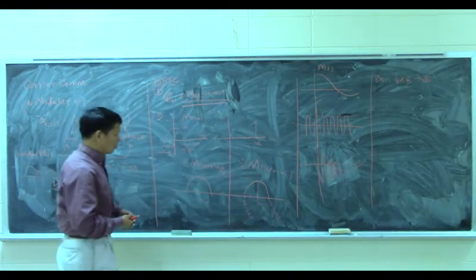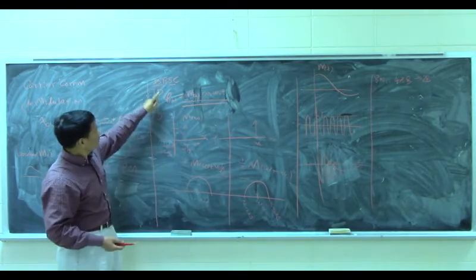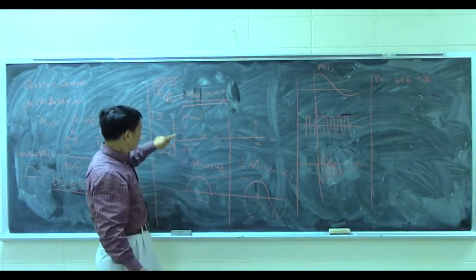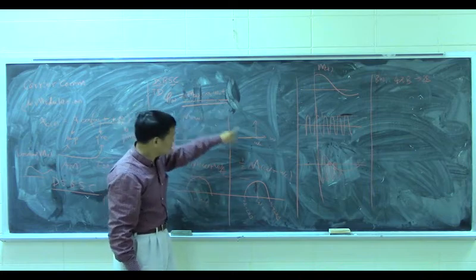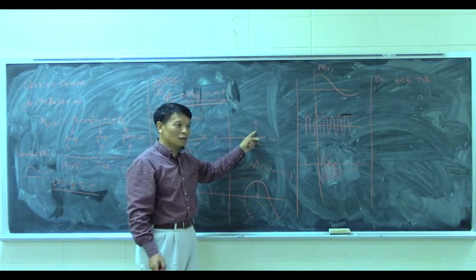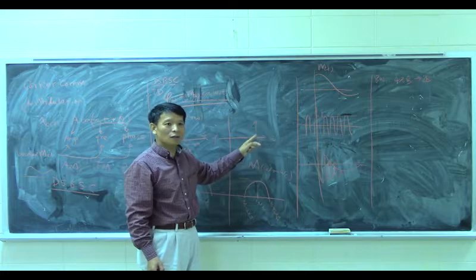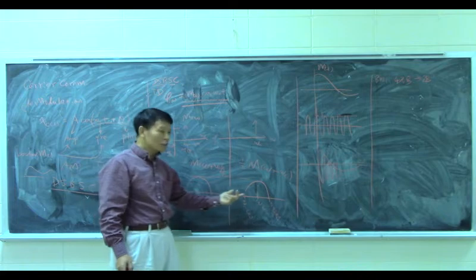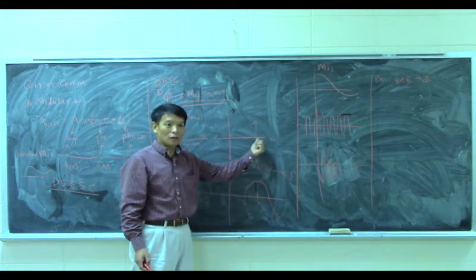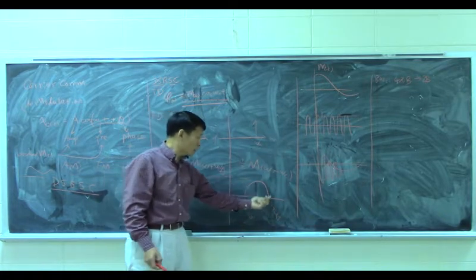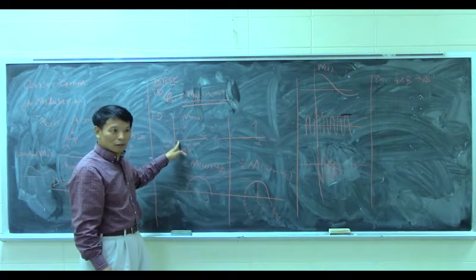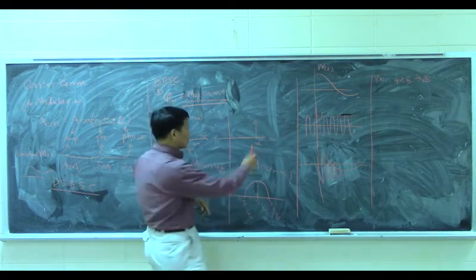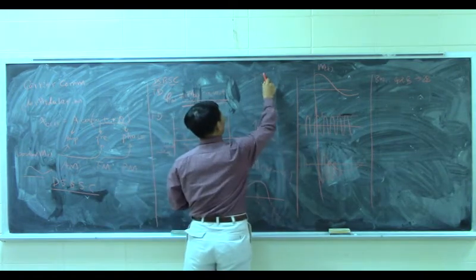The bandwidth is double. Why is it called suppressed carrier? Look at this one. In the time domain, we multiply this signal with this, so we do have this single frequency here. But after the multiplication, do we still have this information here? No, it's not here. This is totally the baseband information. We do not have any frequency from the carrier. For example, suppose the carrier equals 100, very large.